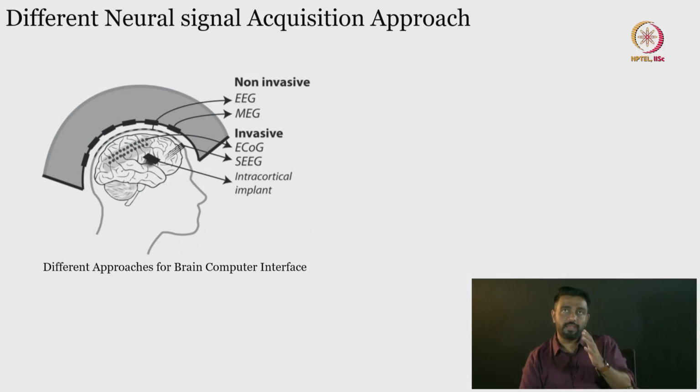So, that is where the difference is, but the first question that will arise is why EEG has lower voltage or lower potential than ECG and EMG. The reason is that the impedance provided by the skull would reduce the signals originating from the brain. That is only one of the reasons; also, the muscle movement of our heart and of our muscles is way higher compared to that of the brain. So, the signals originating in the brain are of lower potential. Now, I am putting this in very easy terms for you to understand, not really bookish terms, so that we understand how to measure those signals and what kind of different devices we can fabricate.